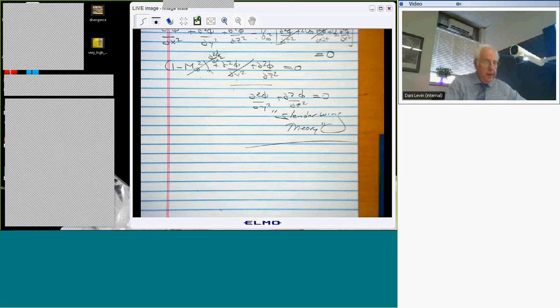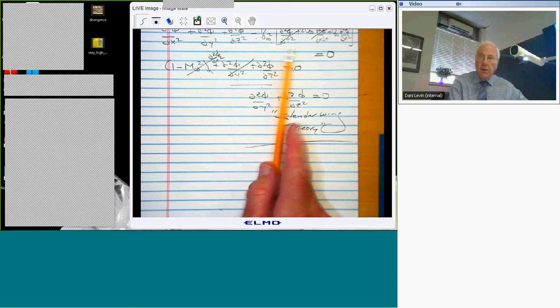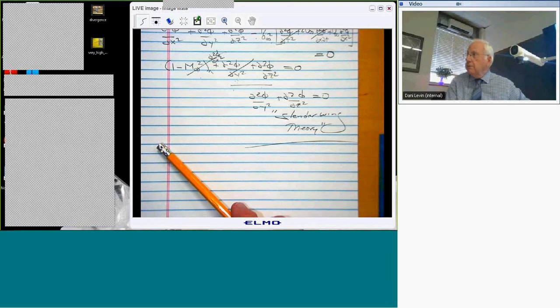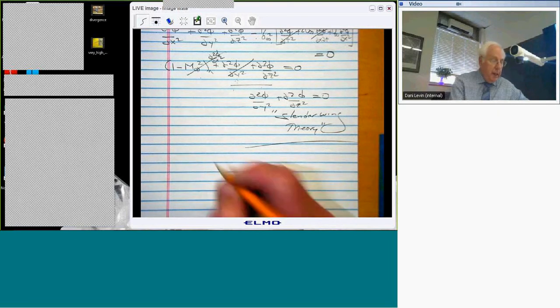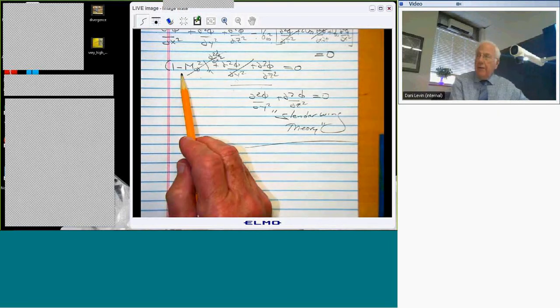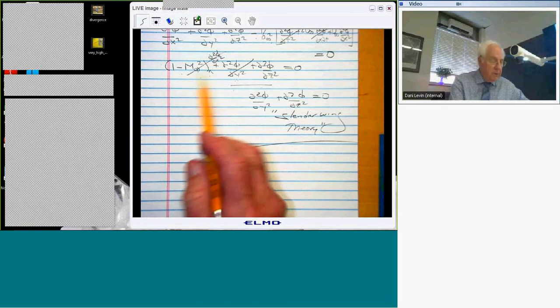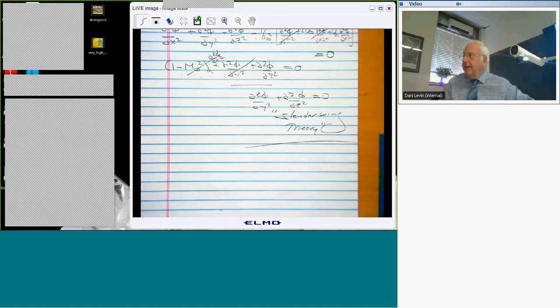On the other hand, for a very high aspect ratio wing, where this term is not terribly important and this term goes away, and certainly for a 2D airfoil, the theory just breaks down entirely. Okay, and it's because you have a cancellation of two terms, essentially, right? And if this were a plus sign, aerodynamics would have gone down an entirely different path.